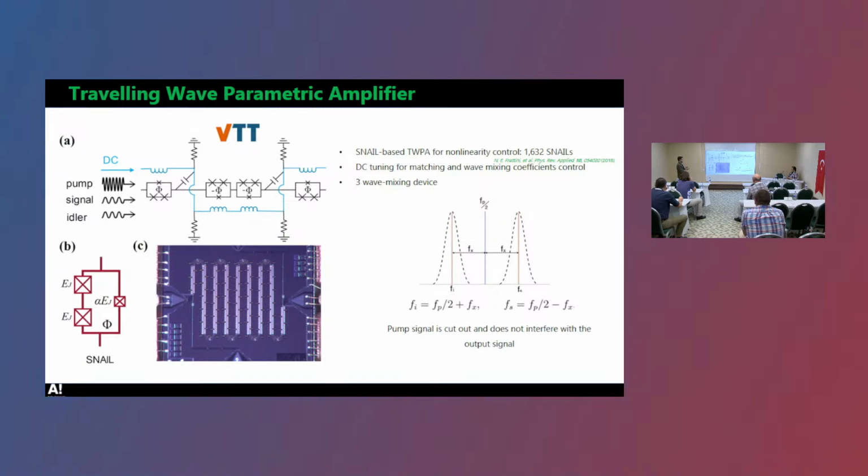and if you want to operate it as an amplifier, you send your signal into this device, and you send the pump as well. Now the pump is not transferred through the flux, but directly inside the device. And then you can design your medium in such a way that the energy of the pump will be transferred to the signal, and the longer the amplifier, the higher the gain you get.